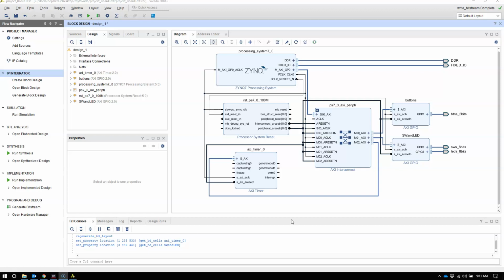Good morning. So I wanted to go over a few things related to Vivado to Xilinx SDK code transfer for the AXI GPIO and the MIO GPIO that we were doing this week. Here is a block diagram similar to what you did yesterday with one AXI GPIO for the 5 buttons. One AXI GPIO with 2 channels.